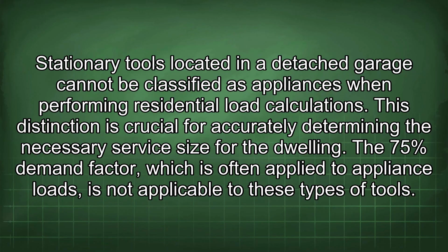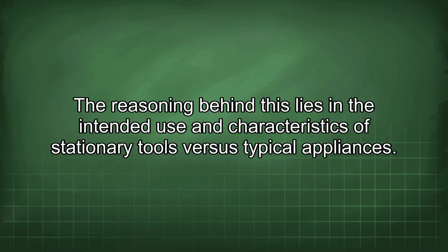Stationary tools located in a detached garage cannot be classified as appliances when performing residential load calculations. This distinction is crucial for accurately determining the necessary service size for the dwelling. The 75% demand factor, which is often applied to appliance loads, is not applicable to these types of tools. The reasoning behind this lies in the intended use and characteristics of stationary tools versus typical appliances.